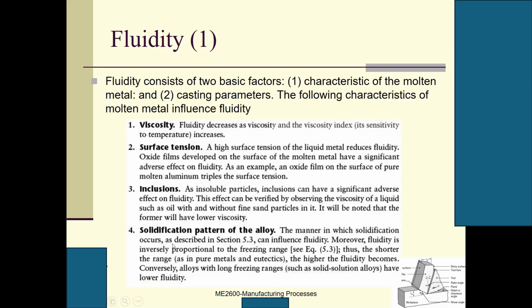This is inclusion. Another one is the solidification pattern of the alloy. The manner in which solidification occurs can influence fluidity. Moreover, fluidity is inversely proportional to the freezing range. Thus, the shorter the range, the higher the fluidity becomes.